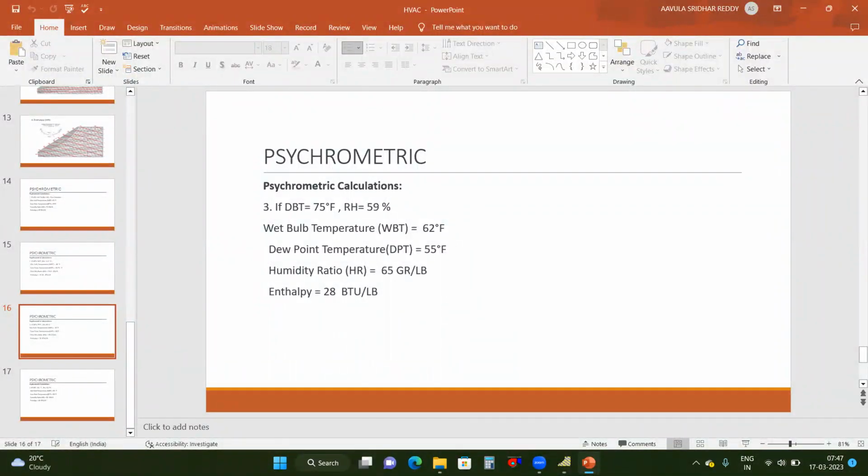When you are doing it for the room condition or outside weather condition, the first criterion is the dry bulb, which we know, so it is mandatory to enter. For example, if you are designing for any area in India, for the high temperature you can search the ASHRAE handbook and get it manually. So we need not worry about this; the dry bulb temperature we will always get.